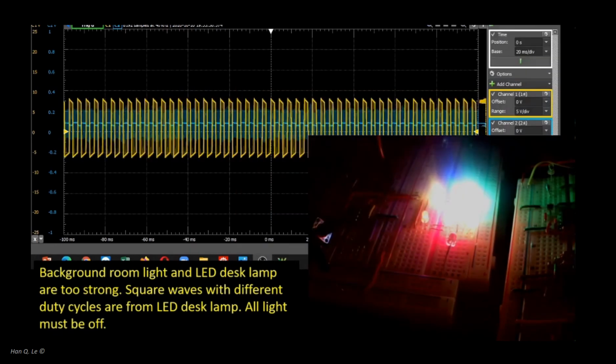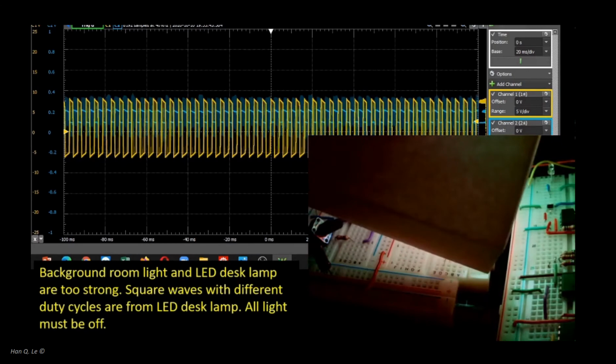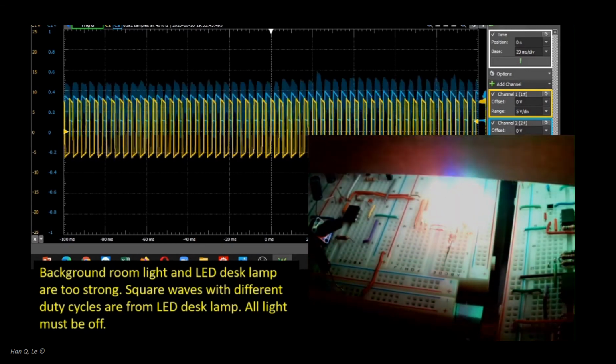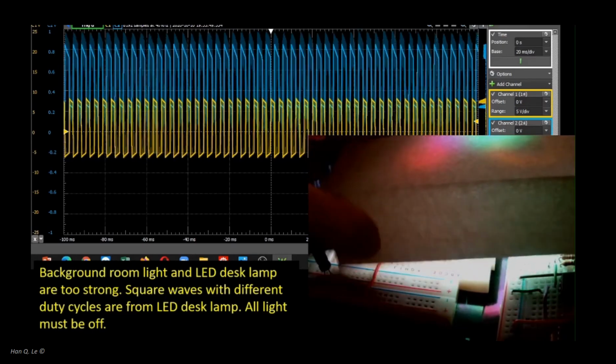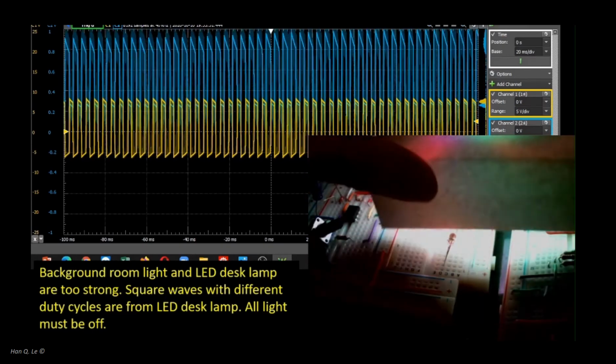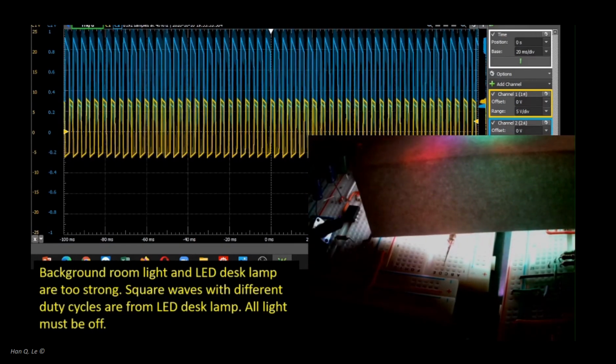The oscillator was allowed to run at higher frequency than previously. The LEDs predominantly emitted light in the vertical direction. The photodiode also faced up, which detected light from the ambience. Hence a cover can enhance the coupling between the LED and the photodiode as well as blocking ambient light for a more accurate measurement.